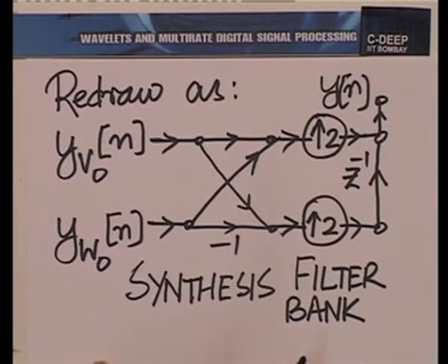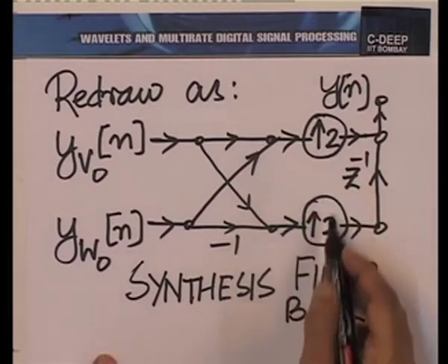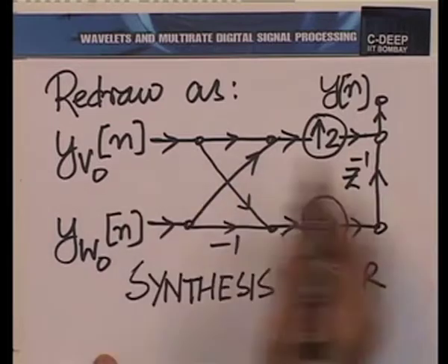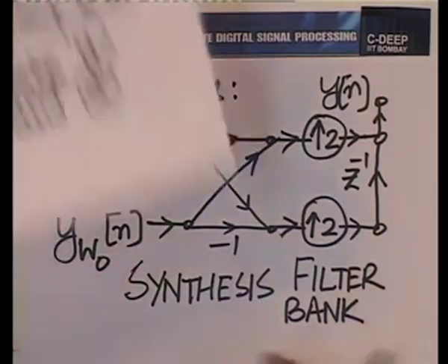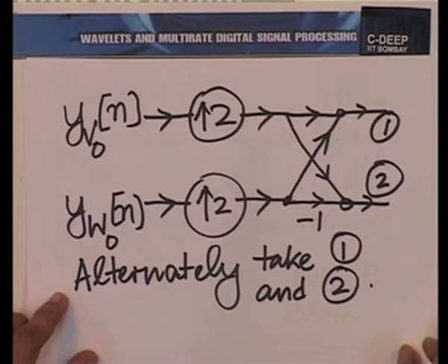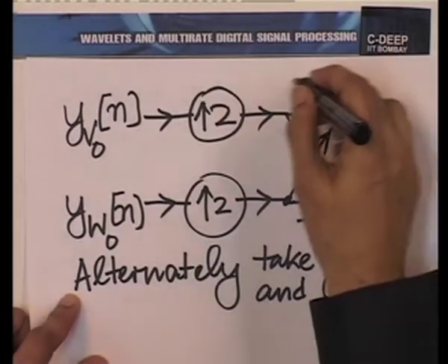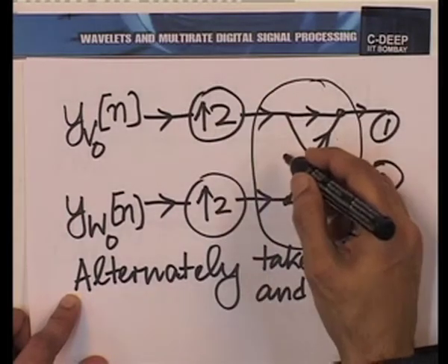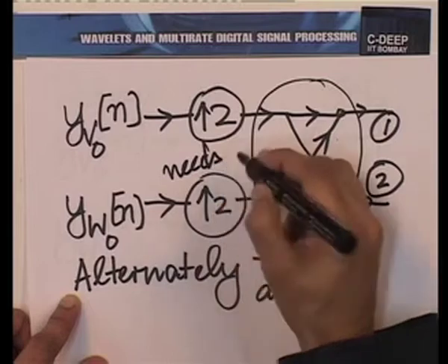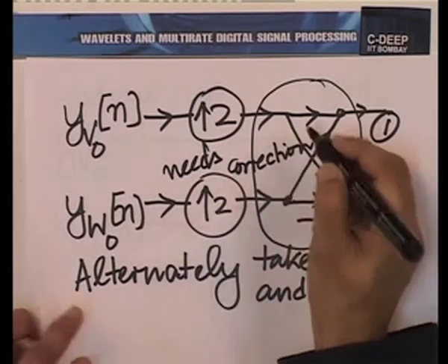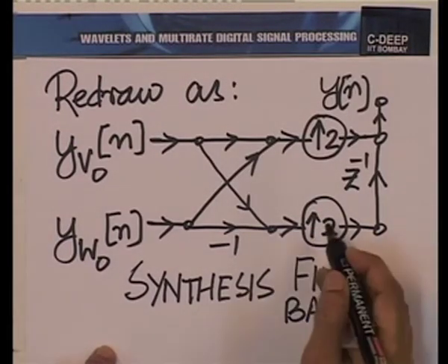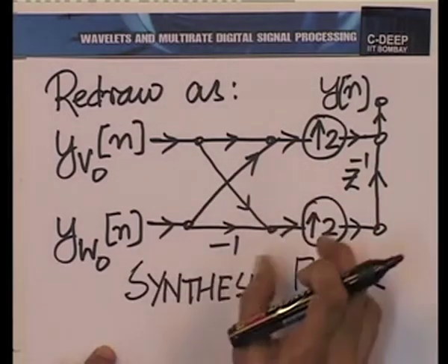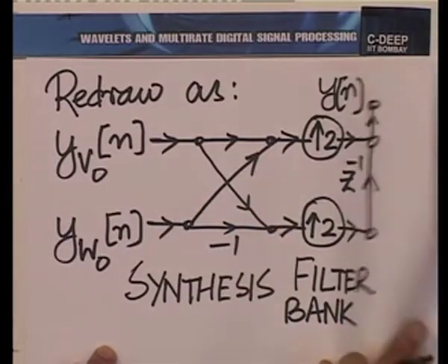And if we will only take a minute to understand that this upsampling operation can jump back and forth here. So, here when we drew this diagram, we were not quite correct. This is intuitively okay, but this needs to be corrected. In fact, now we have the corrected version emerging from here, and let us draw that corrected version by placing the upsamplers back here. Remember, the upsamplers commuted with this operation here. So, if we do that, we have the following structure.